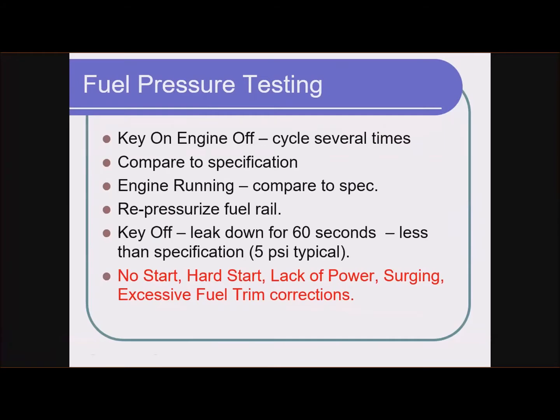Now, most of the time when you start an engine, the fuel pressure will actually go down when the engine's running at idle. So there are various ways that this is done. The early original were a manifold vacuum fed to a fuel pressure regulator. At idle, vacuum is high. That would pull against a spring that would keep the fuel pressure down low.